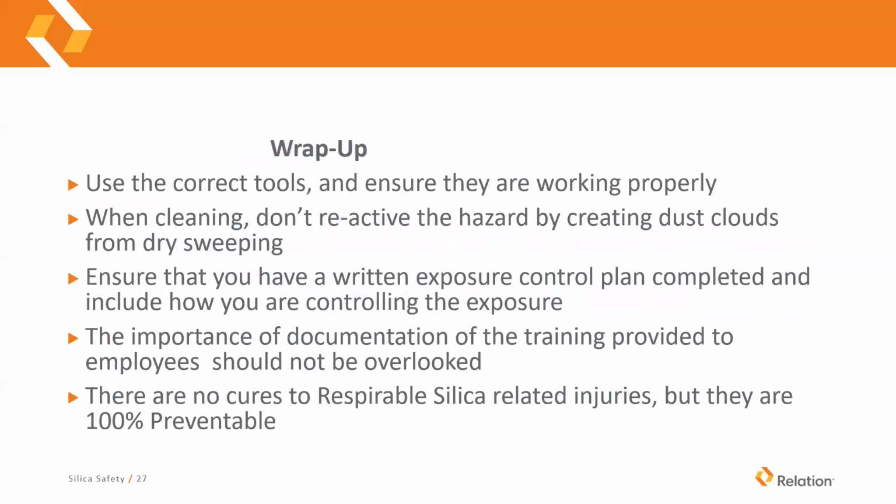All right, so to wrap it up, you want to use the correct tools and ensure they're working properly. When cleaning, you don't want to reactivate the hazard by creating dust clouds from dry sweeping. Anytime you see a dust cloud from when concrete is being cut, it's probably going to contain respirable silica. Ensure that you have a written exposure control plan completed and include how you're controlling the exposure. The importance of documentation of the training provided to employees should not be overlooked.